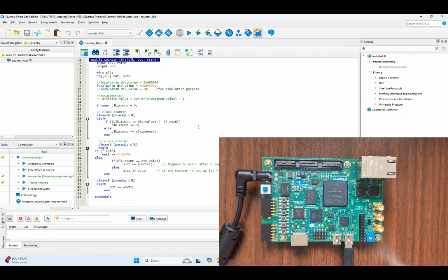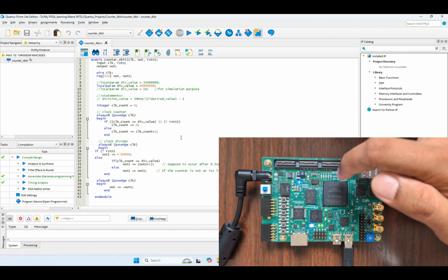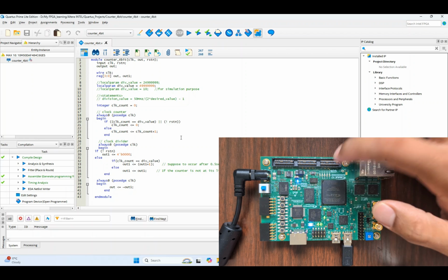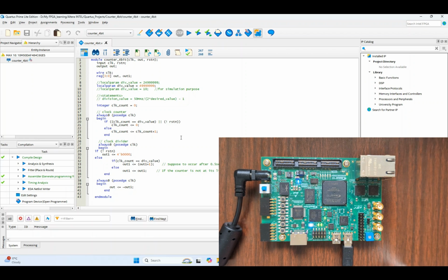Now if we look at the Quartus Prime, again we have already written the code in the Quartus Prime, and we configured the Quartus Prime for Max10 Development Kit. The code shown for the Modelsim and the code here is a bit different. If you remember in our Verilog Basics first video, we discussed that the onboard LEDs in the Max10 Development Kit are connected in active low.